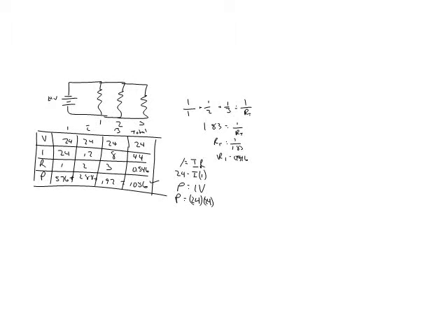Okay, now what we're going to do is I'm going to teach you more rules. There's 2 rules, the junction rule and the loop rule. The junction rule says that anytime you have a junction, a T spot where the current splits, you can add up those junctions at that point to equal the total current. And that's because current is in parallel and it's added in parallel and it's constant in series.